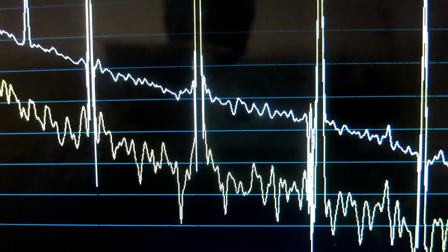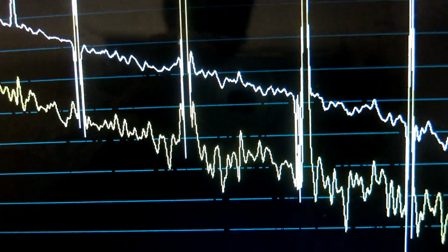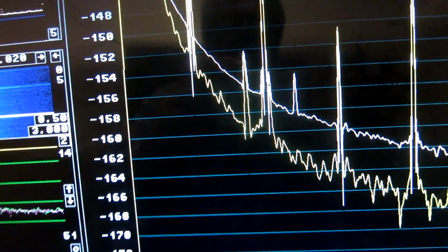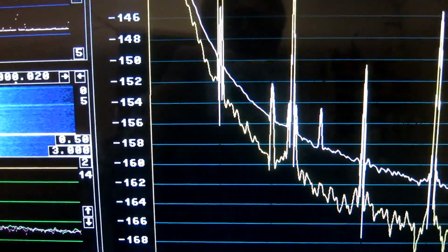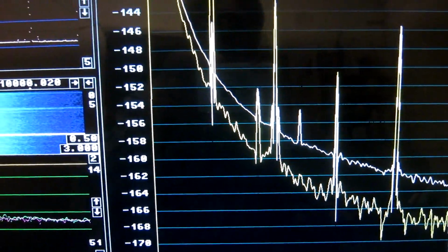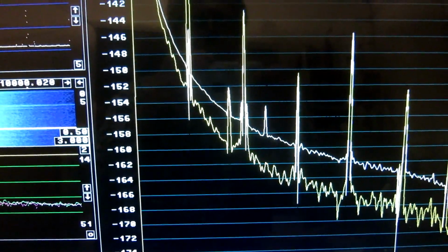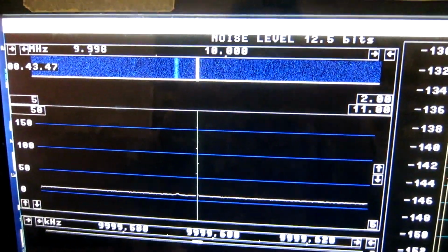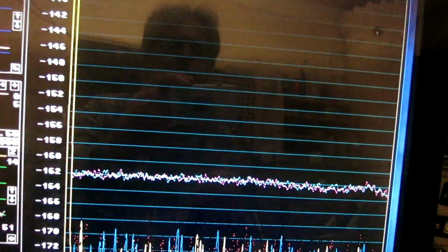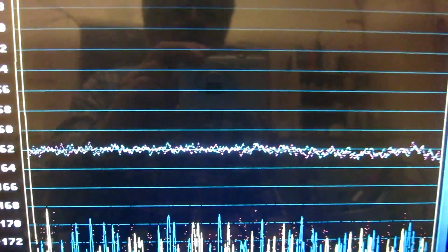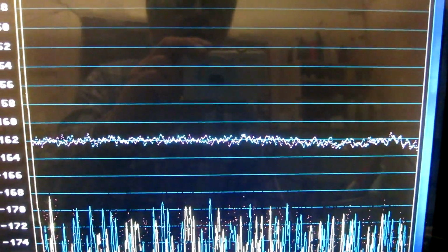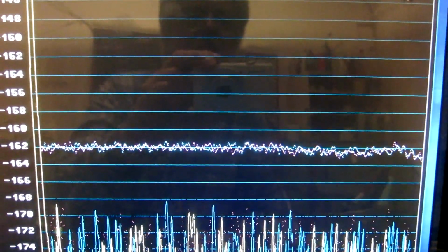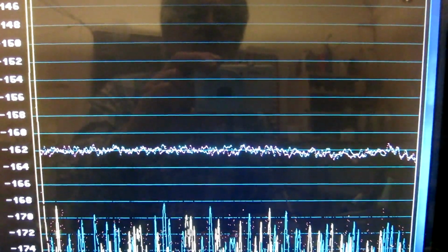Here is the old, and that's the new. The difference is small. So at very close range I can see noise from the attenuator and phase noise. I have enabled the internal generator just to show to myself and also to you that the amplitude spectrum, the power spectrum of the demodulated phase noise is flat.